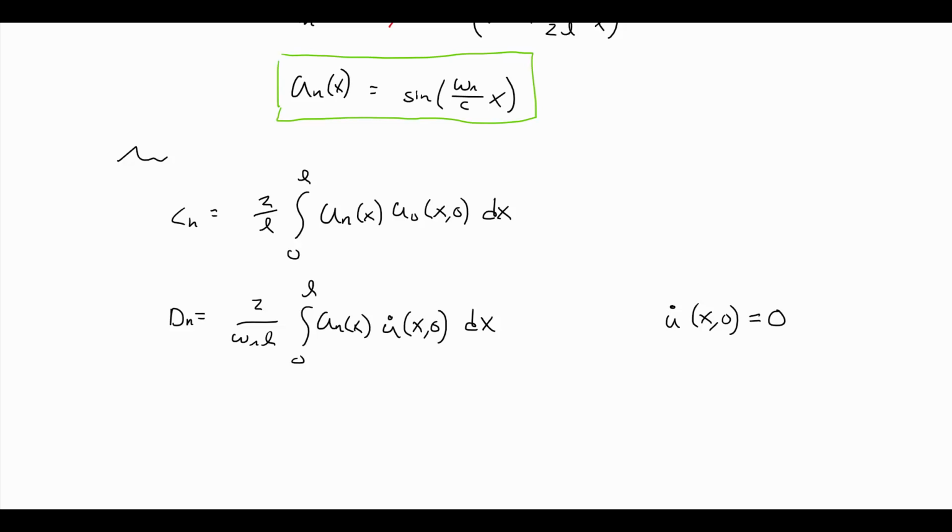We're going to use the same idea here, that u of x, 0 initially is going to be P, which in this case is F0, our applied force, divided by EA, and that's going to be a function of x in this case. So when x is equal to little l, that is the end of the beam. That's how far that point is going to deform from its initial condition. But when x is 0, when we're at the wall, then we're going to find that u is 0. There's no deflection, and that should be the case.